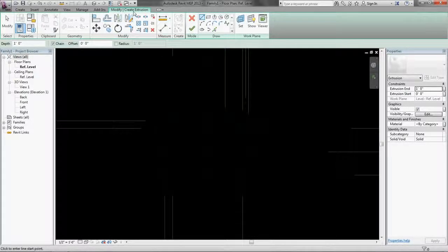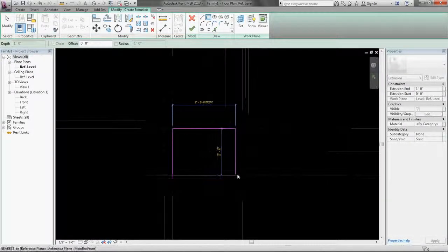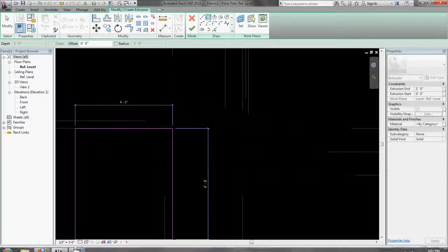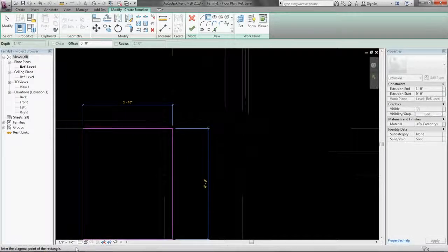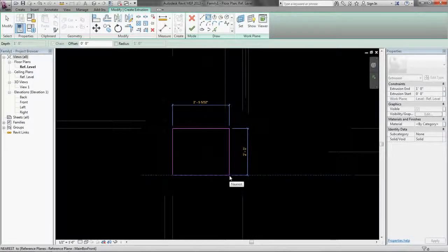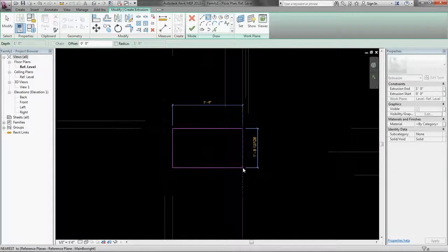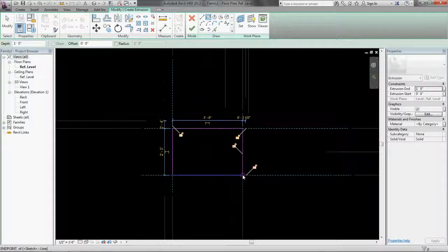And so this tab comes up, and you can draw different things. So the shape we want to draw is a box. So we go up here, select Rectangle, and make sure we're drawing on the right planes. So main box back, main box left, good. Click once. This is main box front, and I'm looking down here. When you mouse over a plane, it'll tell you what the name is. So as I mouse over here, you can see it's saying reference plane main box front in that lower left corner. Then likewise here, it's saying main box right. So the intersection is where I want to be.